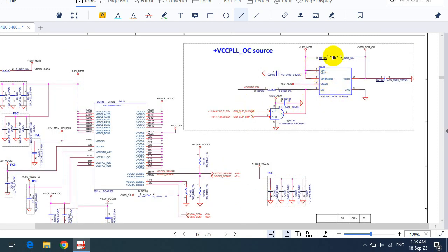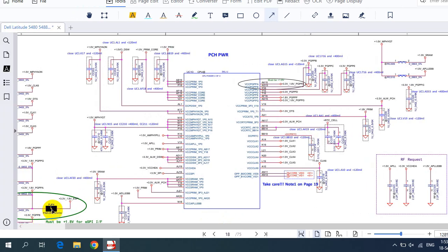Here we have an IC, and here we have an amplifier. This is basically an amplifier. For this IC we have the V in, the V out, and the ground. Okay, this connector, as you can see here we have another bridge, or we can call it a test point. You can check or test here. For example, here we have 3.3 volts, so you can check here whether you get 3.3 volts or not.